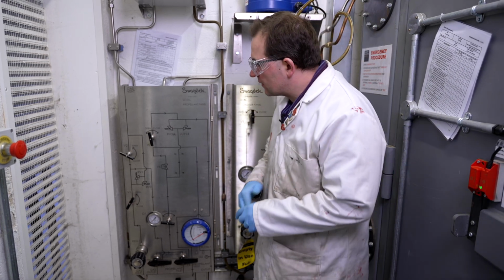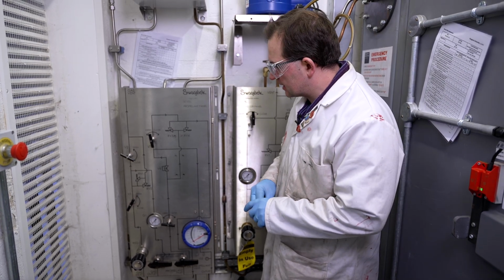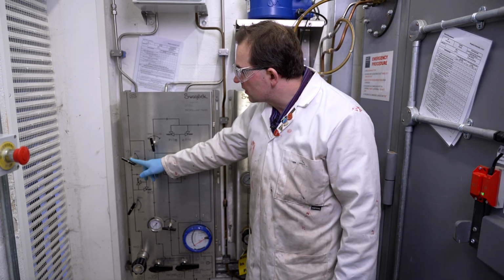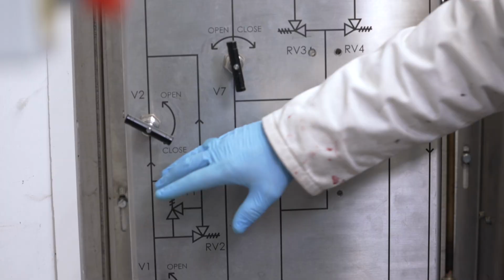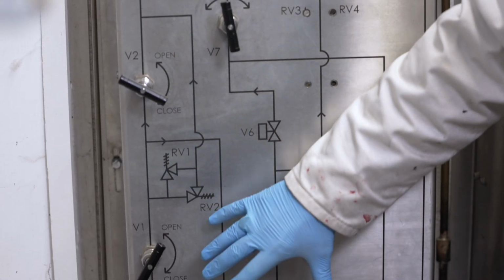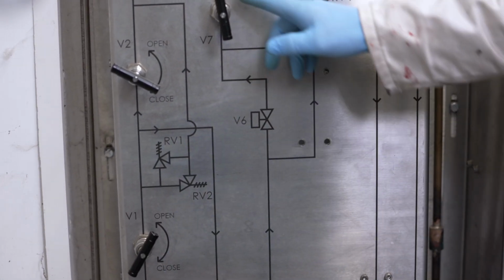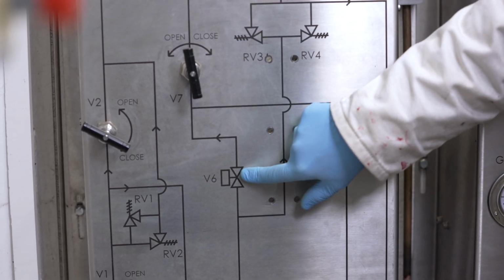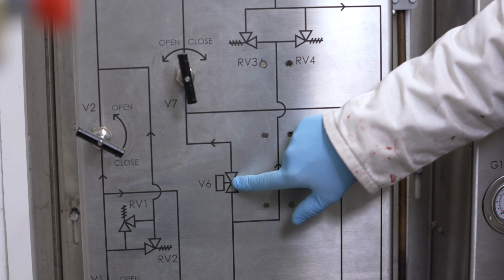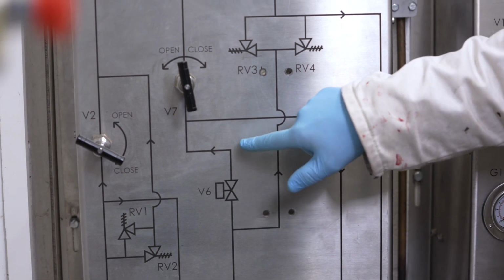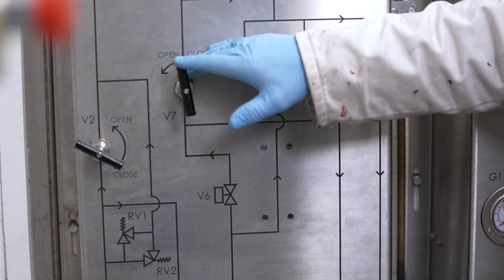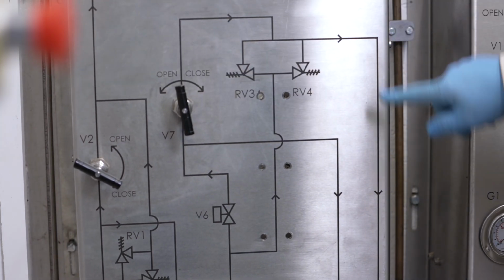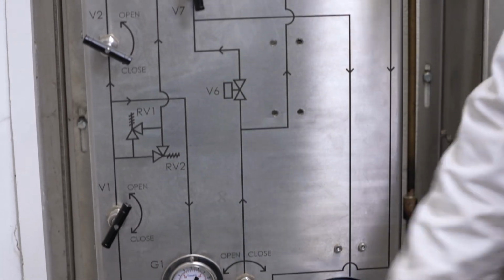Now notice that we've got a few things in place, okay? First of all, I mentioned before about the vent valve. So we've got a vent valve here to be able to vent this half of the pressure panel. And we've got a second vent valve, which will be able to vent on the other side of the solenoid valve. So if we needed to, and the solenoid valve was closed, we would be able to depressurize the system by going through either one of these vent lines and out into the open.